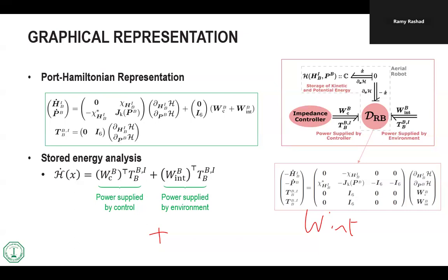Or at least, and this is the trick, even if the impedance controller itself is not passive, I only need to make sure that the controller and the system I have are both passive, such that the closed loop system is passive, and in the end I have guaranteed stability with respect to the open port of the environment. Is this part clear for everyone?